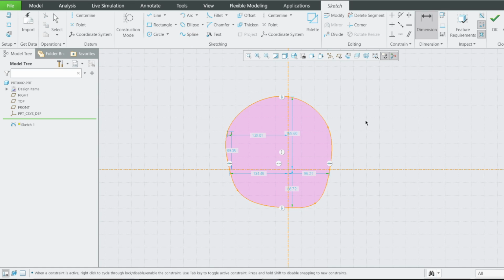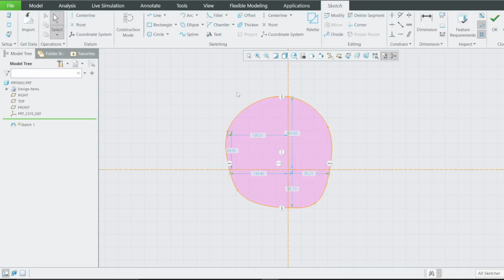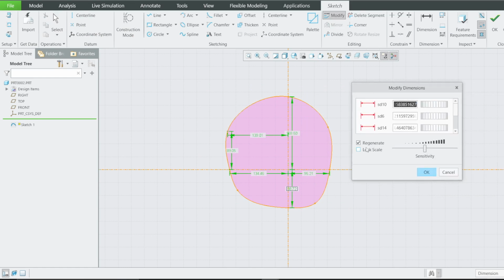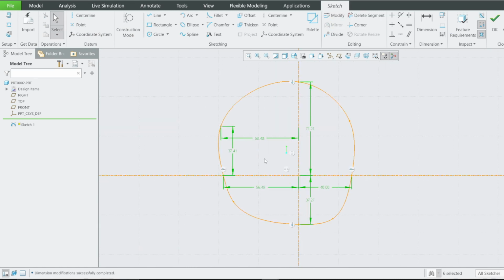And if you dimension this like this, first you highlight everything like that and select, because we want to lock the scale such that when you change one dimension here, for example, if I change this to be 40, everything else the scale is retained.